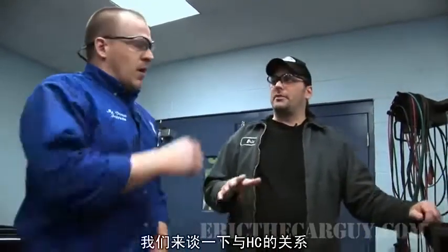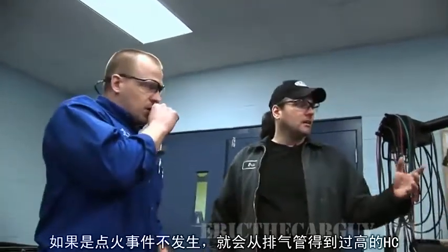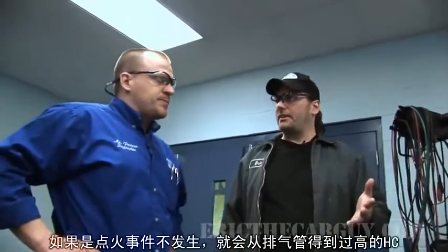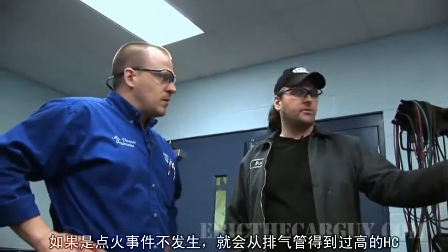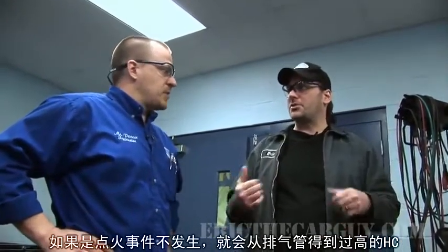All right, let's talk about that a little bit and how it relates to the HC. If it was, say, an ignition event that wasn't occurring, you would have extra HC coming out the tailpipe. Yeah, absolutely. So that's what you're looking to see. But the fact that you don't might indicate that the injector itself is not firing as it should. That's correct. So therefore, the misfire is due to a lack of fuel, which would be seen here with the low HC.